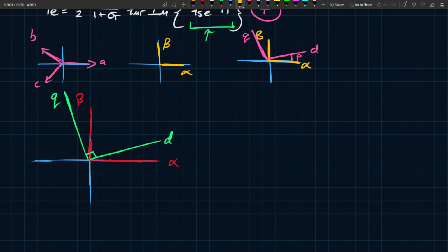And so any current like this, let's say this current, or any phasor, it doesn't have to be a current, let's say this is Is in this case, because that's what we're dealing with. And this is the stator current, right? So any phasor can be decomposed into these two components. You have one component here, and one component here. This component on this side we call ISD, and that's the D-axis component. And this is ISQ. Okay?